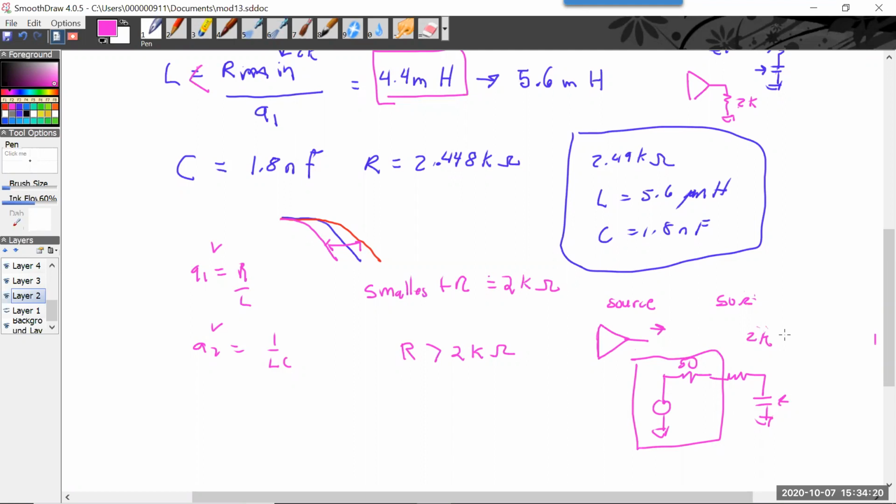But in real design, you can't just say always. Maybe you could say mostly. When I say in this class, I mean we use signal manipulating op amps, which tend to have a 2K minimum resistance. So back to here. That's the minimum.